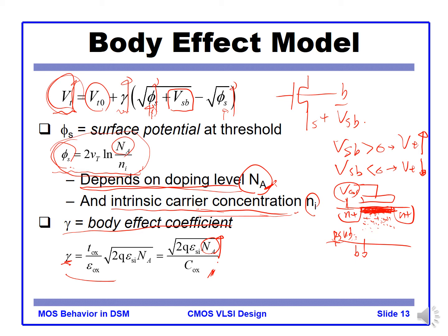So typically there are different VTH provided by the process. There are usually 3 different VTH models: the regular VTH device, the low VTH device, and the high VTH device. Sometimes there is also an ultra low VTH device. So how do we control this VTH for all different devices? We control the doping level on the surface. By controlling that, we can have different VTH devices.